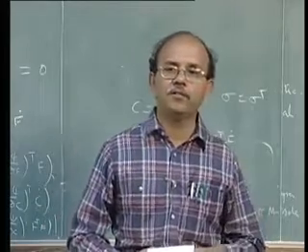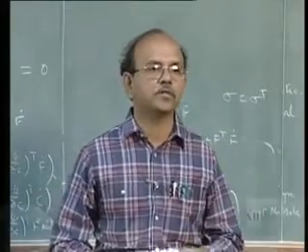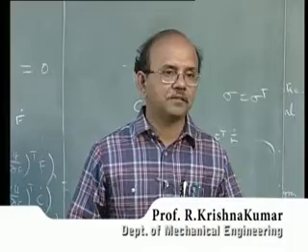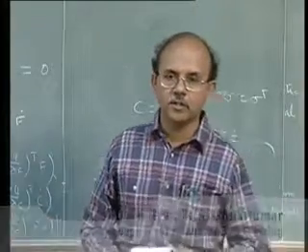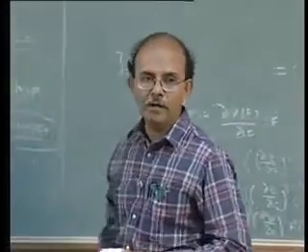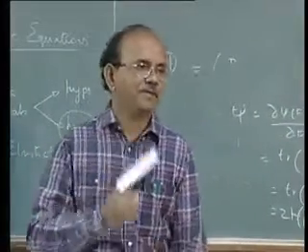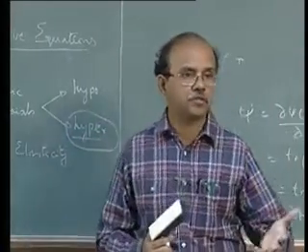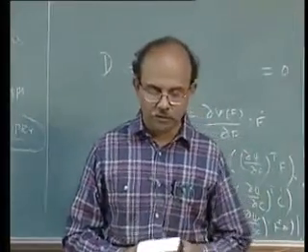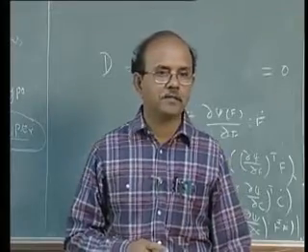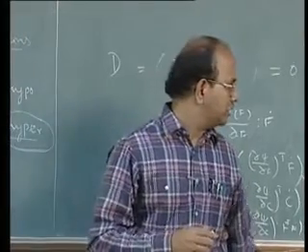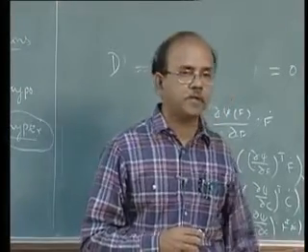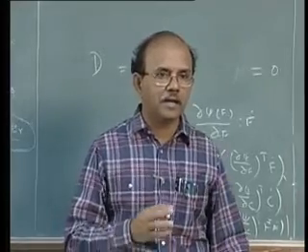Unfortunately or fortunately, we do not use the first Piola-Kirchhoff stress to that extent in computational engineering. You tell me why? Very good. It is not symmetric. So in most situations we use only the second Piola-Kirchhoff stress, and it's very important that we develop the relationship between the second Piola-Kirchhoff stress and